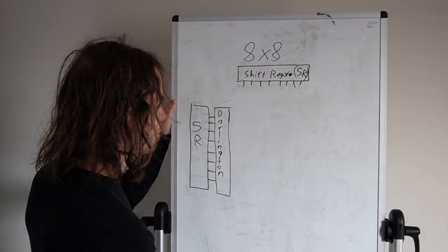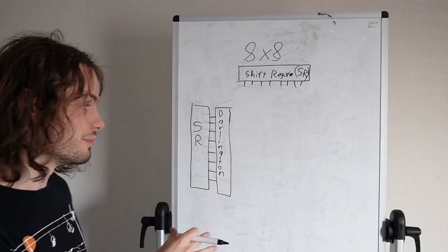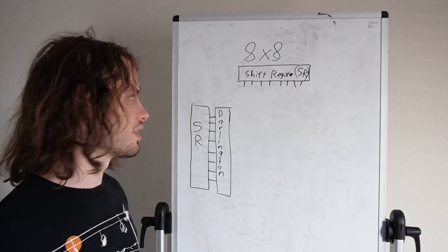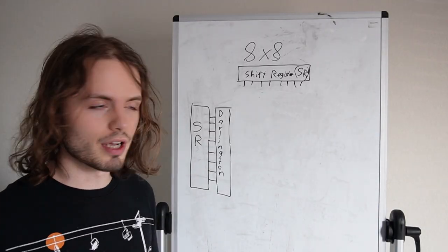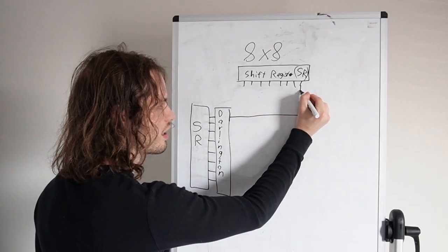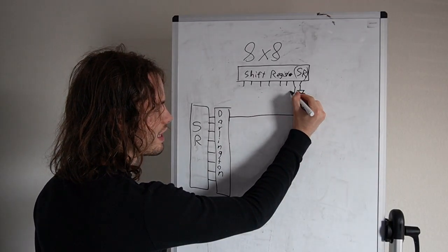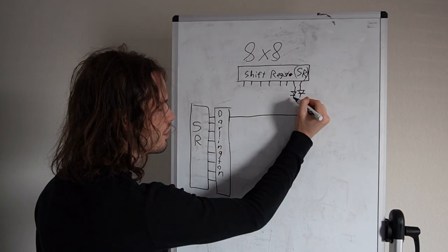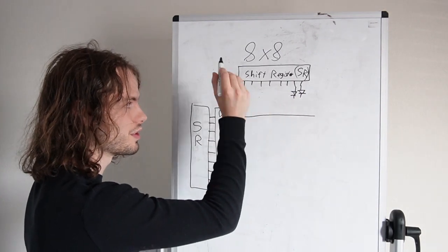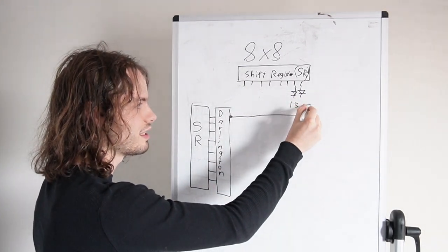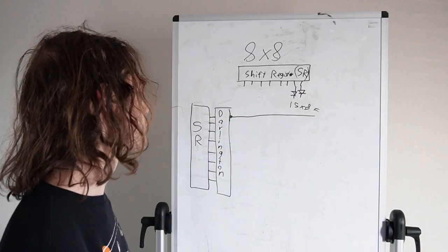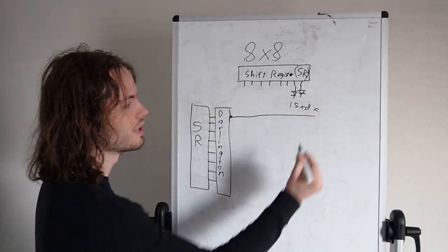Now you also may ask why the Darlington array. Again, it's about a current thing, but the reason I use a Darlington and not just another transistor is because each of these rows will connect to all of these LEDs going down into it. So if I want to drive a single row, this terminal here has to take 15 milliamps per LED, and there's 8 of them, so it's 15 times 8. Whatever that is, it's a lot of current. Well, it is milliamps, but